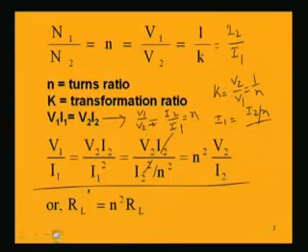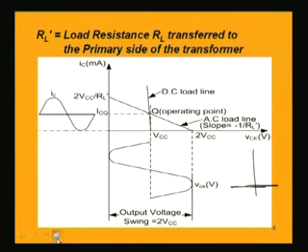Starting from the DC value, it will be increasing and decreasing. That point is the Q point, which is the DC point or quiescent point. We know at that point the value of the collector to emitter voltage was VCC and the collector current was, say, ICQ.